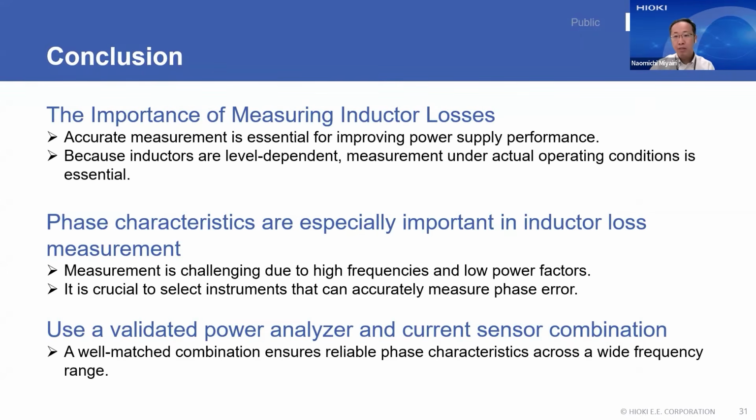Because inductors are level-dependent components, it's important to perform measurements under actual operating conditions using a power analyzer rather than relying solely on LCR meter results. As we've seen throughout today's session, phase characteristics play a particularly critical role in inductor loss measurement.